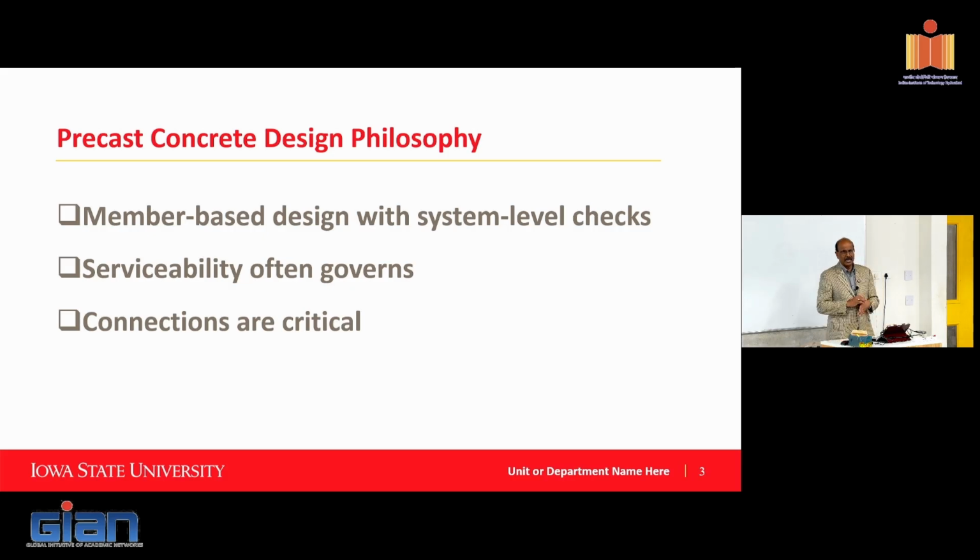Typically in precast, pre-stressed concrete, the serviceability governs the design, not strength. So if you know the service level load, basically you have your product, because the handbook standardizes the components for you automatically. I will continue to emphasize that connections are critical, and we will talk about the different types of connection that get used in precast.